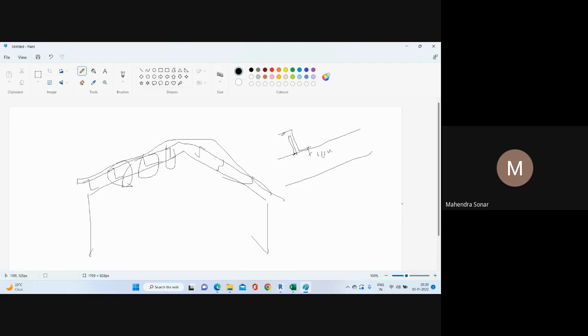So on site, when we fit this Z purlin, you can just add the 2 bolts. This gap is 10. Then at the bottom of this Z purlin, you need to give a minimum distance of 35. And this is the 70 distance between the 2 bolts, and again 35. So your plate size is approximately 35. So 1 bolt here and 1 bolt here. Okay, and here welding.